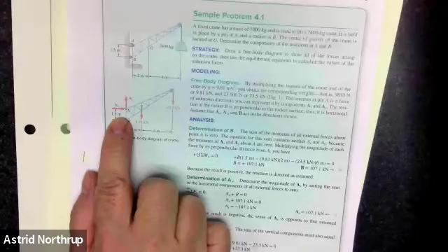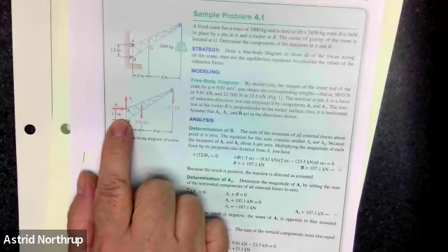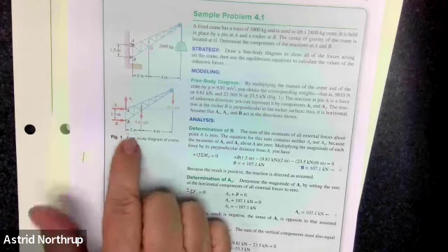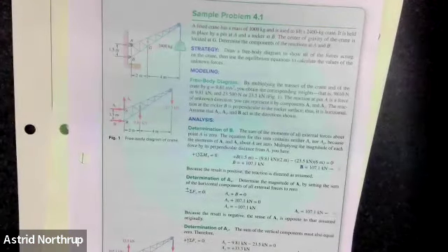You could also probably suppose that A is pulling the crane back into the wall. So you might see that this is drawn incorrectly. I would recommend that you always draw your reactive forces as positive, because otherwise, if you get a negative of a negative, that means it's really positive. If you always draw them as positive and then do your math as though they're positive, if they are in fact negative, it will come out a single time in the math and you won't be confused by what a double negative means, or just forget it and put it in incorrectly. So you don't have to follow that.